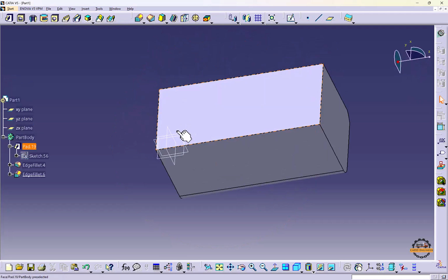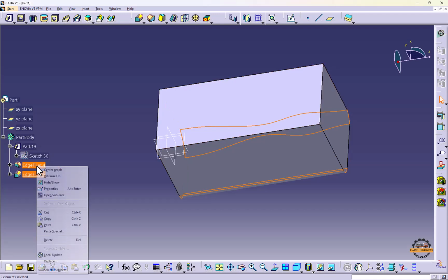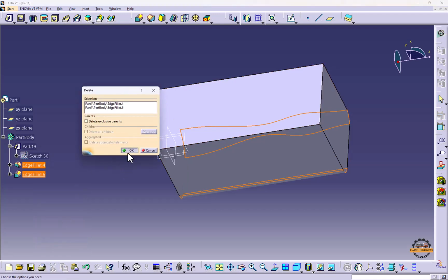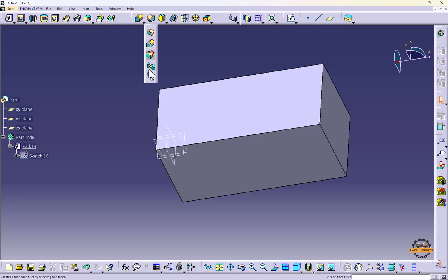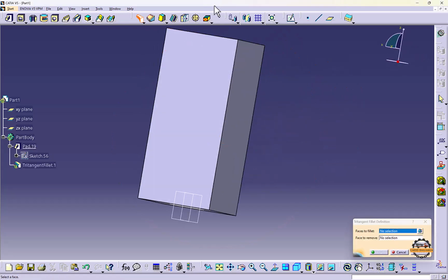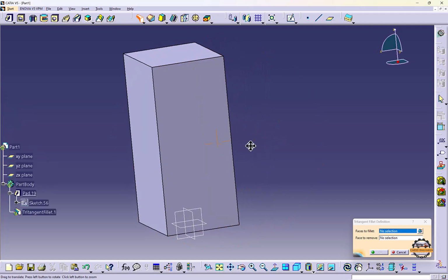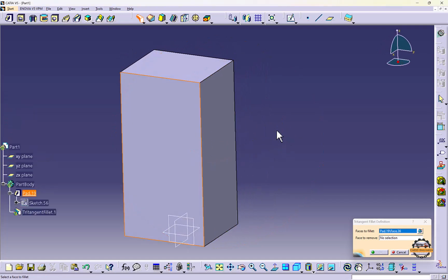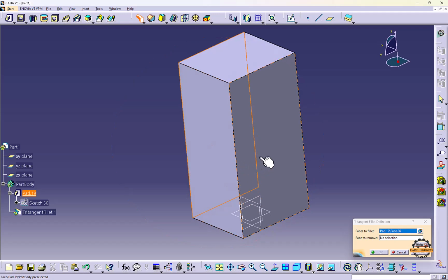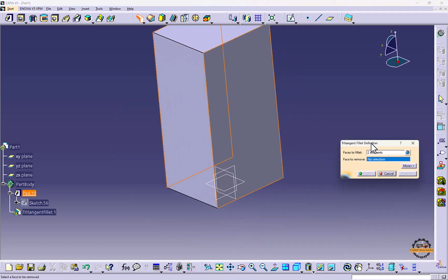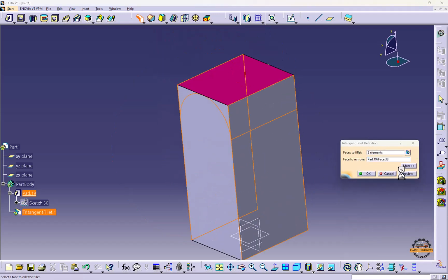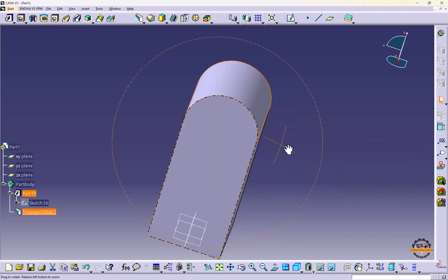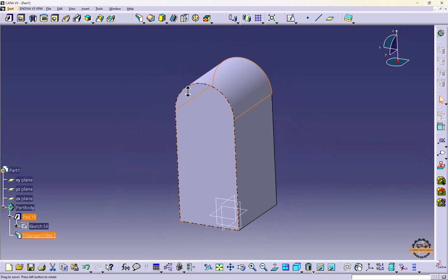Now we can do one more thing, the full round fillet method, which is called the tri-tangent fillet in CATIA. We'll see how to do that. For that, we'll take this tool from here, called the tri-tangent method. We need to select any 3 faces in sequence. I'll take 1, I'll take 2, and the third one is the one we have to remove. So you can see that it makes a round on that face. That's called the full round fillet method.